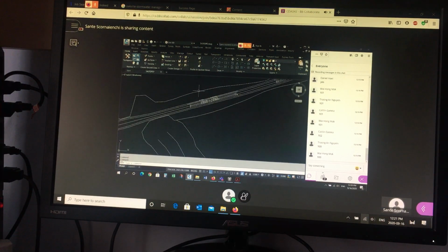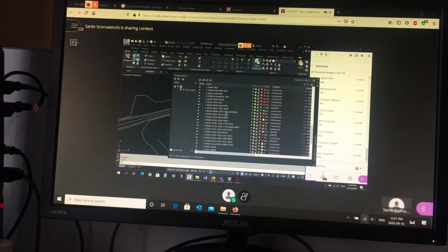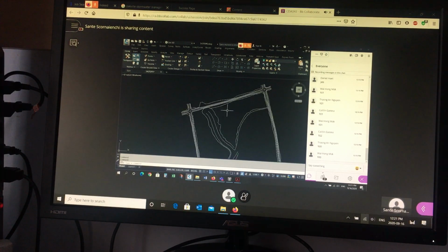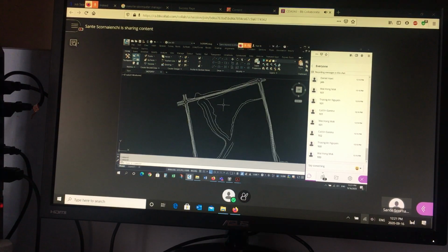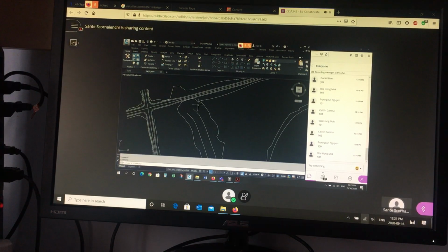The ones you don't want to include, if you go to those T-dash layers, you don't want to include anything related to water main. So all 4 of those layers you don't need. Anything related to storm, you don't need. Anything related to sanitary, those you can turn off. All the other T-dash layers should be used as break lines, but not the service layers, not sand, not storm, not water. So this will actually tell the surface, and connect the dots in sequence.